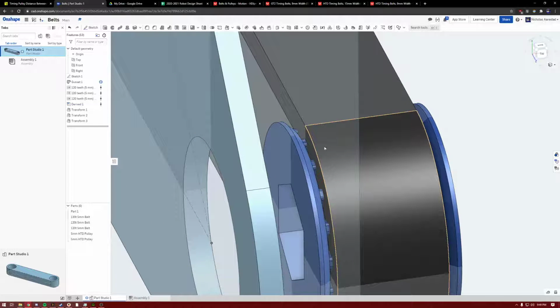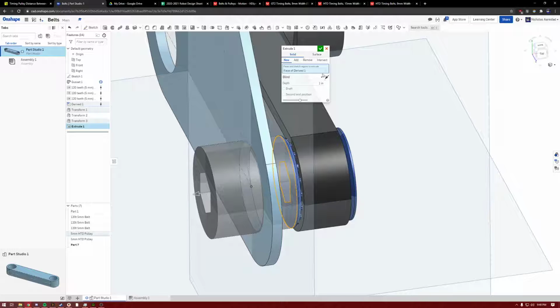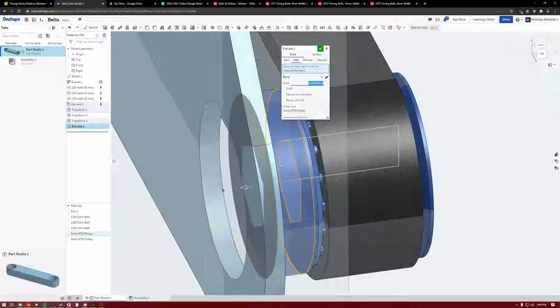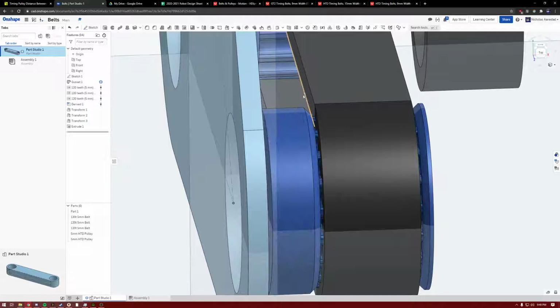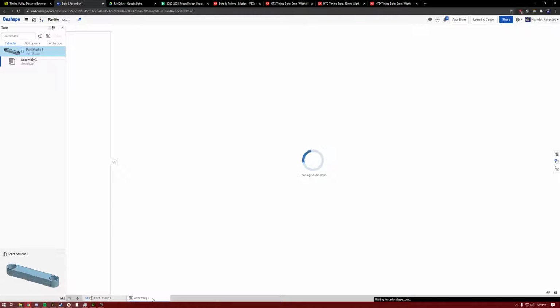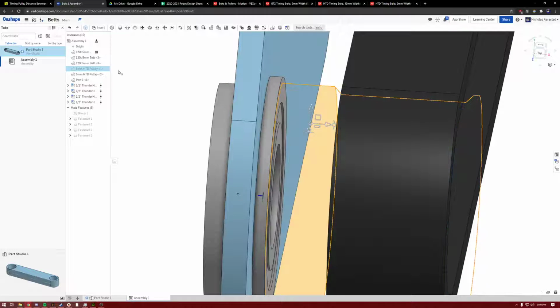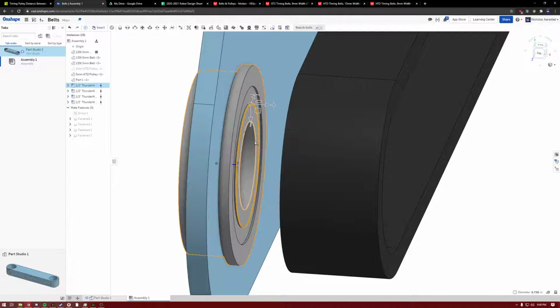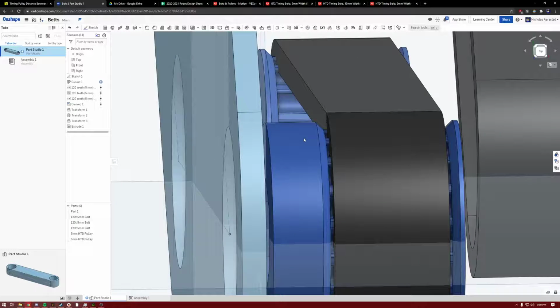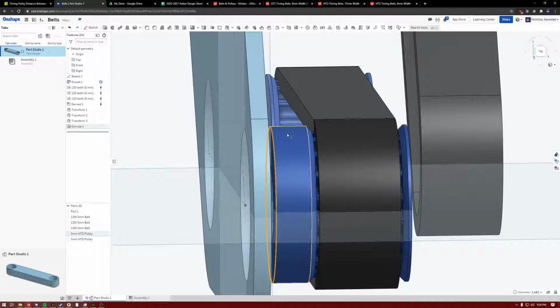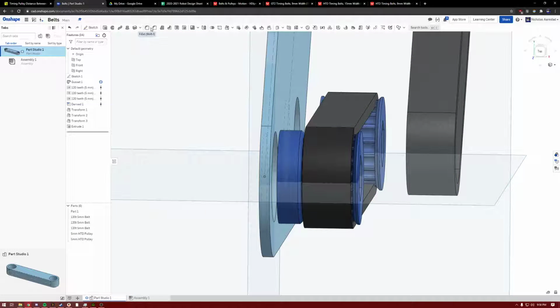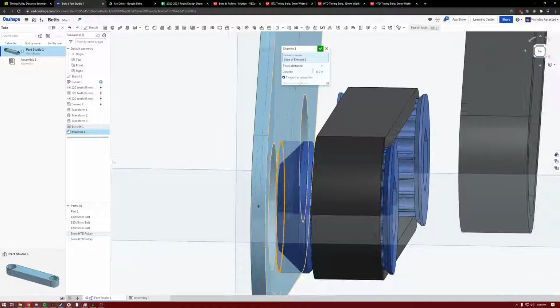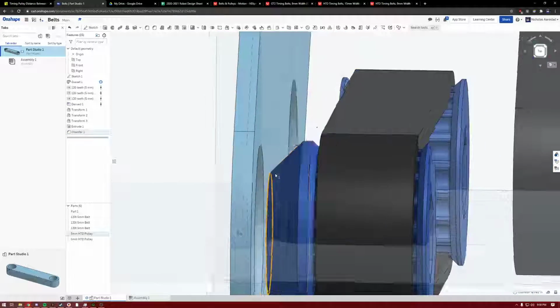That's just silly. So what I can do then, because this is a derived part, I can just add that straight onto there. And then, because when you do a pulley, you only want to contact the inner race, this inner bit, because otherwise it'll have friction on a static part. So I think that's 0.75. So I want to take this down to 0.75 or less. So I can throw this on there. 0.2, it's reasonable.